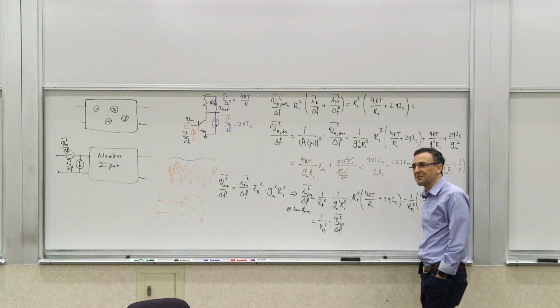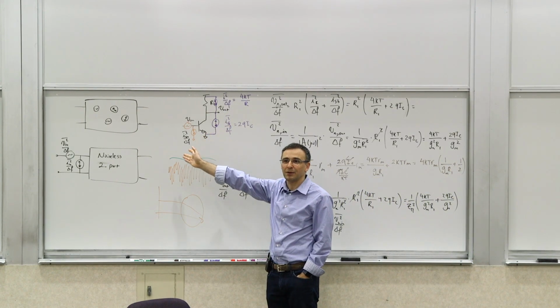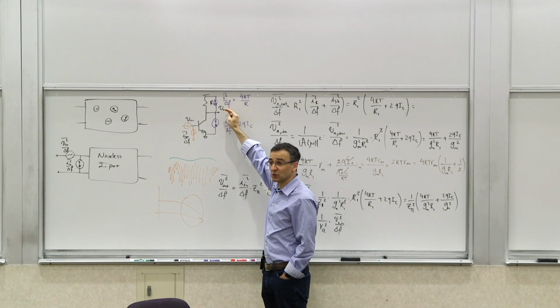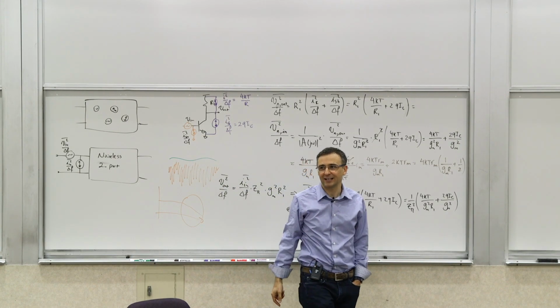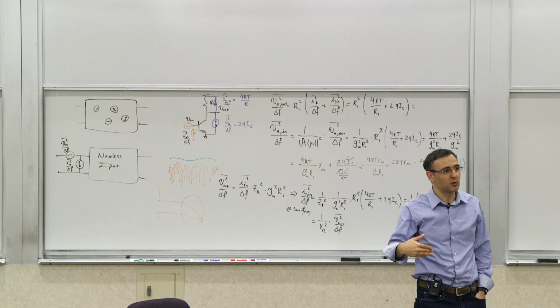So you need to think about where you're measuring it, right? A lot of times, for example, you're measuring at the output where it's already amplified. So you want something whose input-referred noise is less than the output noise of this thing. So you may be able to compute that. So that's interesting. There are ways of getting to lower and lower noise calculation.